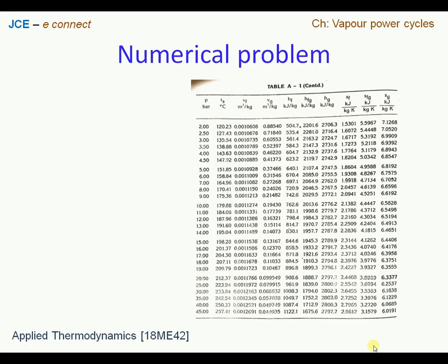So here we have table number A1, and we are focusing on the last column, which pertains to the dry saturated condition of entropy. Our target is S1, because S1 is equal to S2, which is 6.3249. We have to see where exactly we are going to find this value from the saturated vapor curve line, which is represented here as SG. So let us proceed one by one.